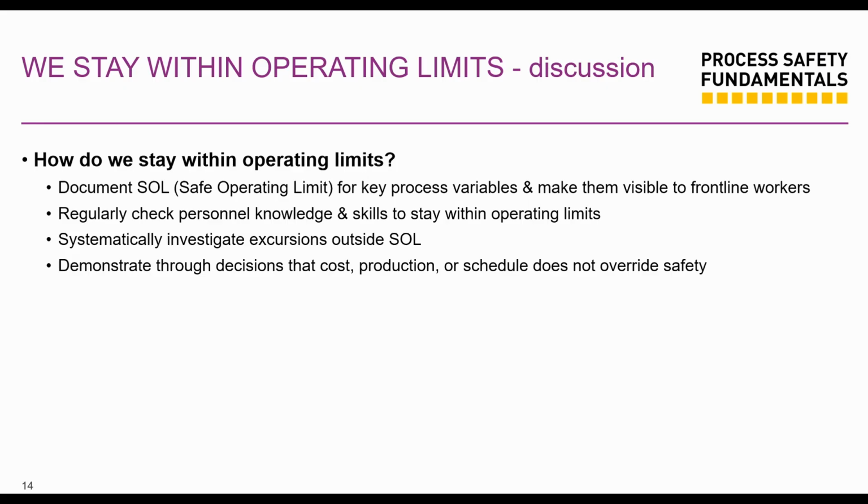Then also systematically investigate excursions outside our safe operating limits. We're supposed to investigate those excursions. And so when those happen, when you have those pressure spikes, those trips, actually carry out an investigation to see what the root cause is, and it could be something a lot more sinister than you're aware of.